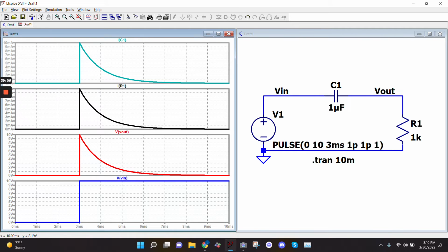Is the blowing up basically electrons going through the dielectric? Yes. I don't know, maybe. It's a discharge between the two plates. The resistance of the dielectric is too much, and then it actually arcs through it, and that's why it pops. I know that in Electroboom's video, he had that happen where he put way too much voltage on the capacitor, and he had these little sparks popping through the plates. He talks about how it basically shorted the two plates together through the dielectric. There was too much voltage for the dielectric to handle, and so the electricity was like, all right, we're going to go right through it.